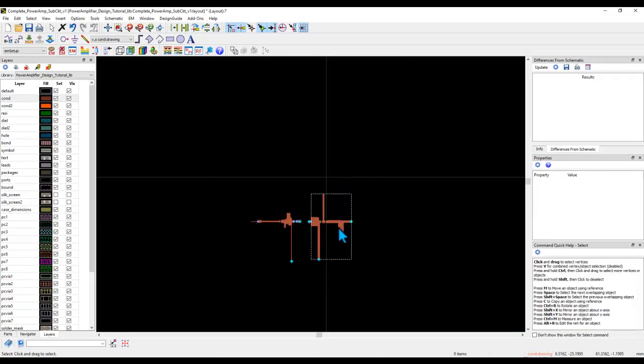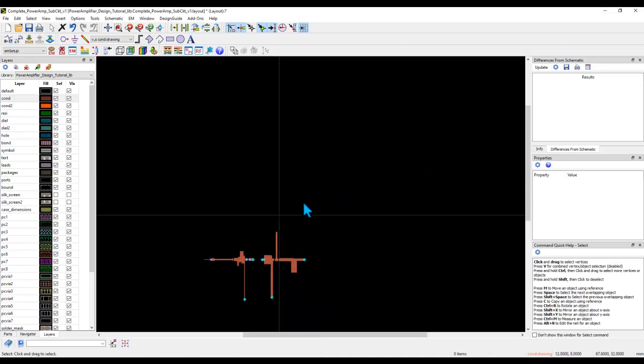So now I do have my rough pieces of the PA design. Now I only need to arrange them in a logical fashion and create the groove which I'm going to cut out of PCB, adjust this overall size of the PCB in the desired PCB area in which I want to design. So in this case, I'm going to assume I need to design a PCB in 2" by 40 mm kind of size. And again, size can be subjected as per your system requirement and how much space you have available.